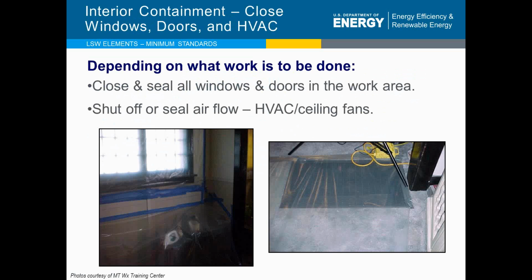Okay, some other things, and we're talking interior at this point in time, and that is, within that work zone, and in some cases that work zone may be quite large, we need to close and seal off all windows and doors within that work area. We need to make sure that we don't have airflow that's just going to pick up that dust and move it all over the place.